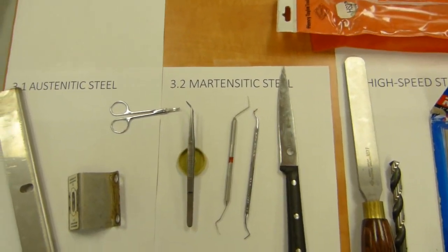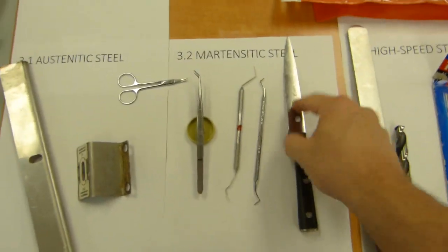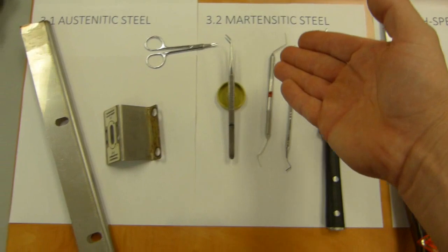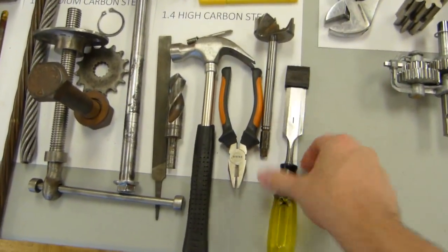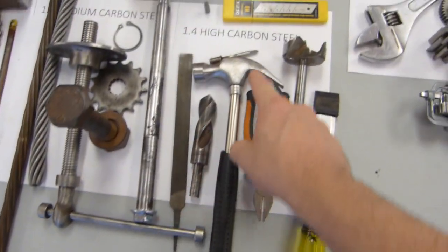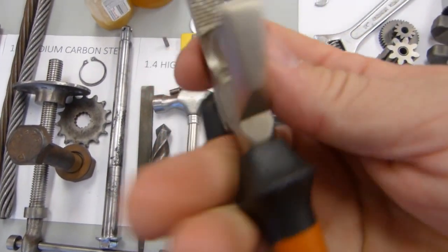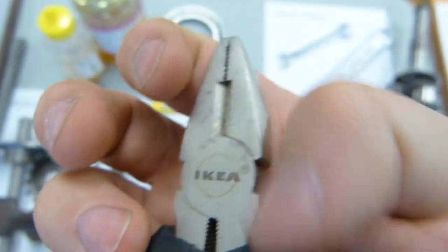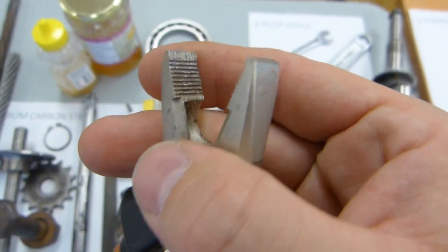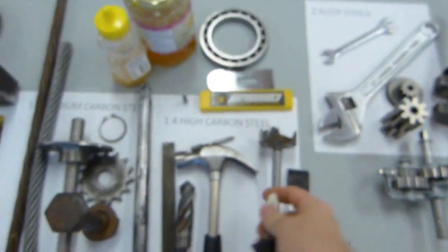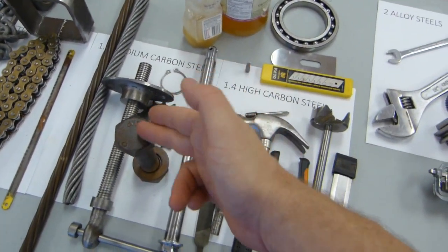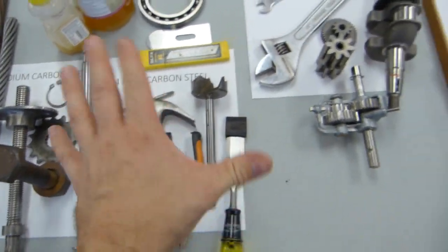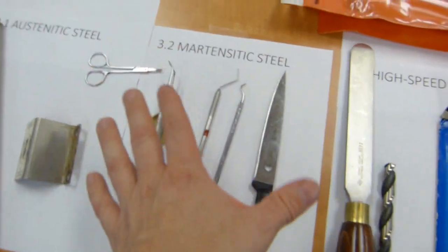These ones are not weldable. Don't even try, it's not going to happen. They have high carbon content, so they can be sharpened. Coming back to the tools here, high carbon steels hold a sharp edge. Edge is not so important on a hammer, but there are small edges on the pliers over here for wire cutting. There, so you get the idea, those beveled surfaces in the middle for wire cutting. And of course the jaws on the pliers also shouldn't deform. They do eventually, especially on bolt heads that aren't much softer than the pliers' jaws. But so, sharp stuff, high carbon content.